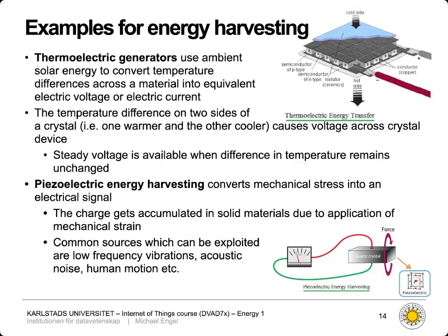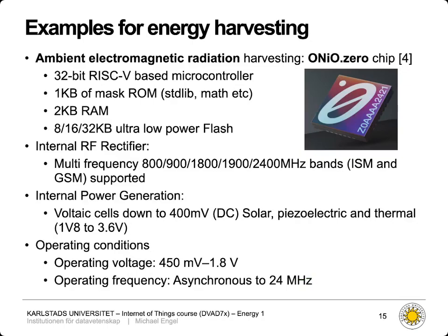So these also have a quartz, and this quartz uses a piezoelectric effect when just provided with some electric energy, and then it starts swinging, and the quartz swings at a certain given frequency dependent on its crystal pattern, and then we have a reliable clock source for our processors. So piezoelectric energy works both ways. And you can use, for example, low frequency vibrations like acoustic noise, human motion, and so on to generate electricity using piezoelectric generators.